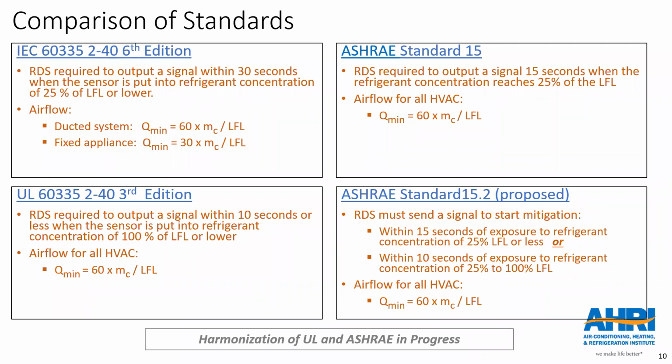Again, 4 boxes, and as you can see, all 4 standards specify the maximum allowable time for an RDS to respond to a level of refrigerant. Now there are differences in this. The IEC has the longest time, but that standard was published before the AHRTI testing results indicated that a response time of 10 to 15 seconds would be better.